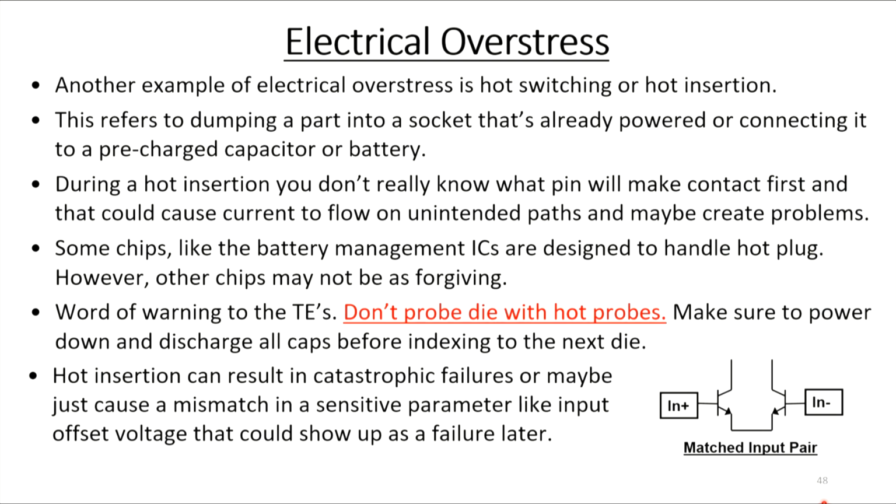Another example of electrical overstress is just hot switching or hot insertion. And this refers to dumping a part into a socket that's already powered up or connecting it to a pre-charged capacitor or battery. During a hot insertion, you don't really know what pin will make contact first, and that could cause current to flow on unintended paths and maybe create problems. Now, some chips like our battery management integrated circuits are designed to handle hot plug. However, other chips, they may not be quite as forgiving.